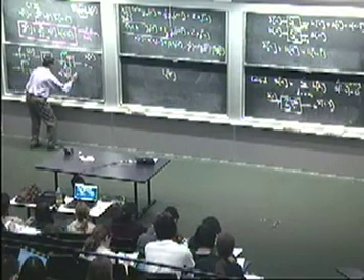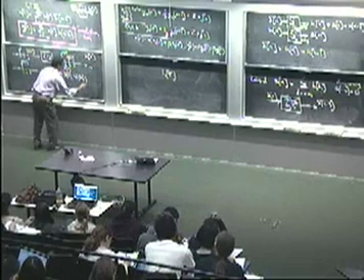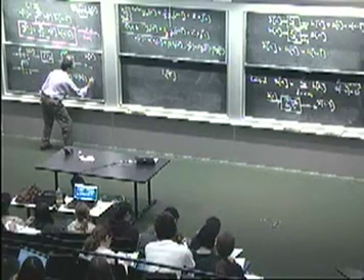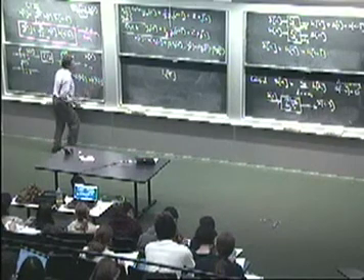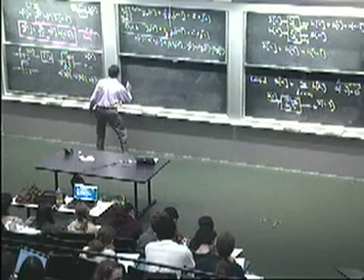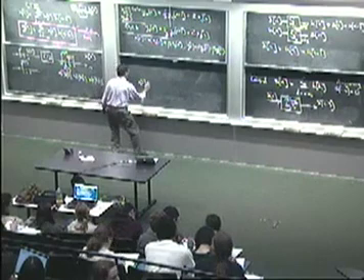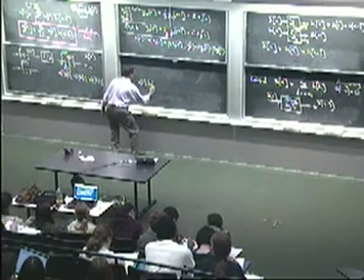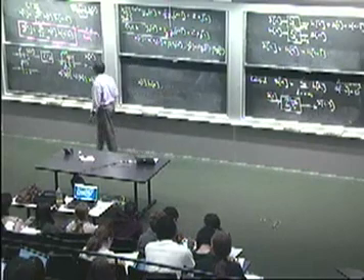Okay, so what we'll get is x[0] times h[0] coming out at the first time, and then x[0] times h[1] coming out at the second time, and then x[0] h[2] at the next time. And if I keep going, I get x[0] h[n] at this time, and so on, right?